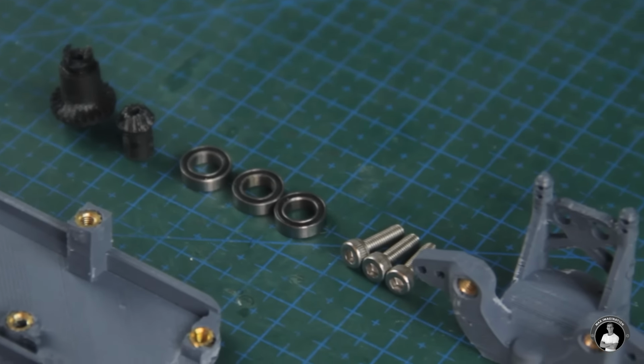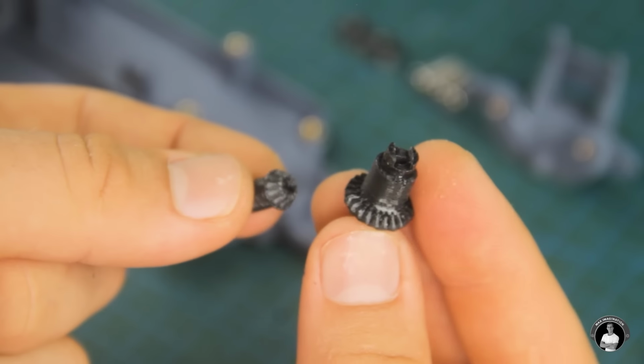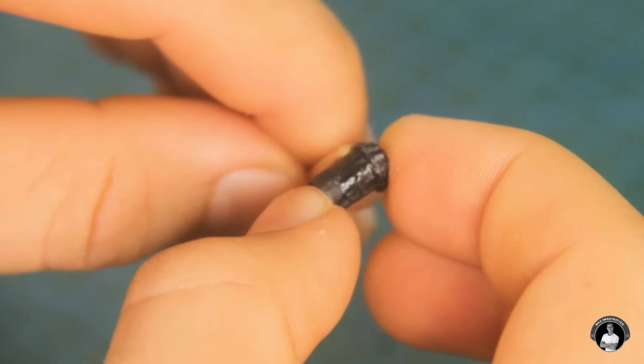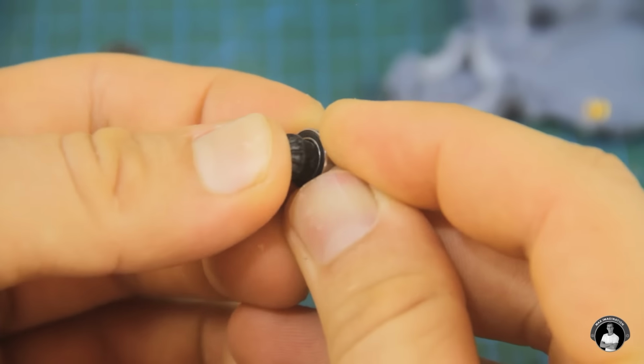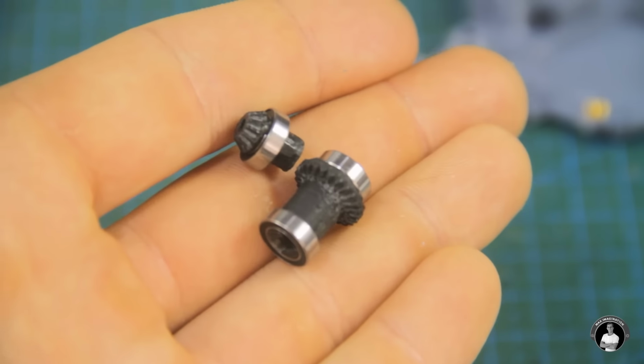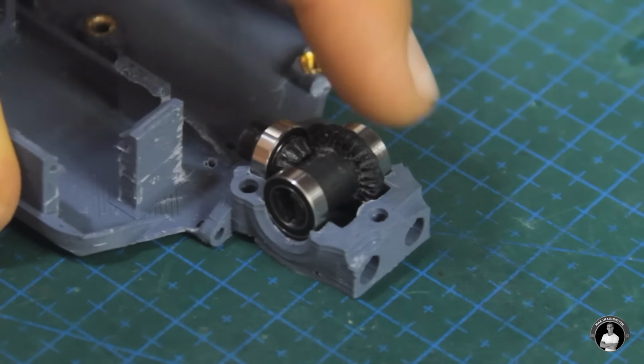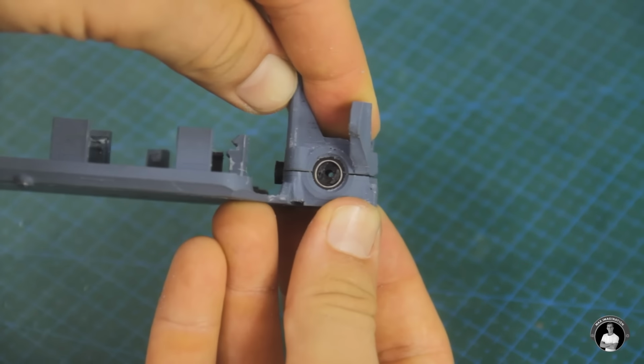Next, we can assemble the front drive gears, which take the motor input through a drive shaft which connects to the front pinion gear that is strengthened with super glue. We can then attach bearings onto these gears like the last and put them in place with the orientation of the spur gear in mind so it rotates with the same direction as the front.